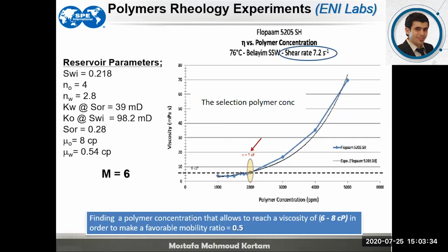That reduction in the viscosity of the polymer would reduce its effectiveness and efficiency, leading to an increase in the mobility ratio. If you design it exactly on 1, it may actually not produce 1 downhole or in the reservoir. It may be greater than 1, might be 2 or 1.5 or something in between. So that's what we are saying.